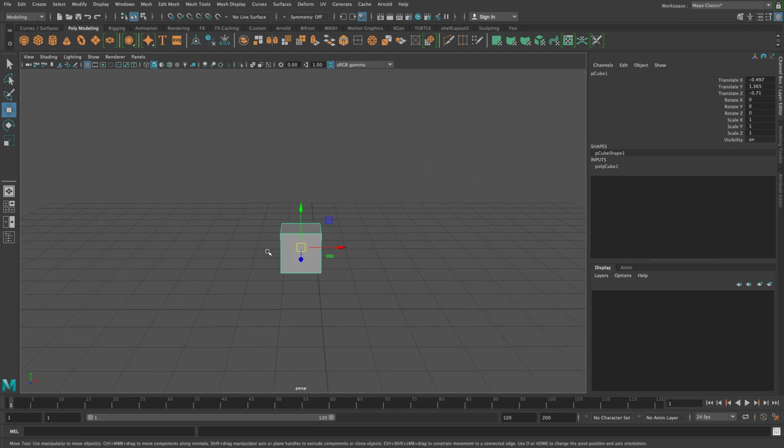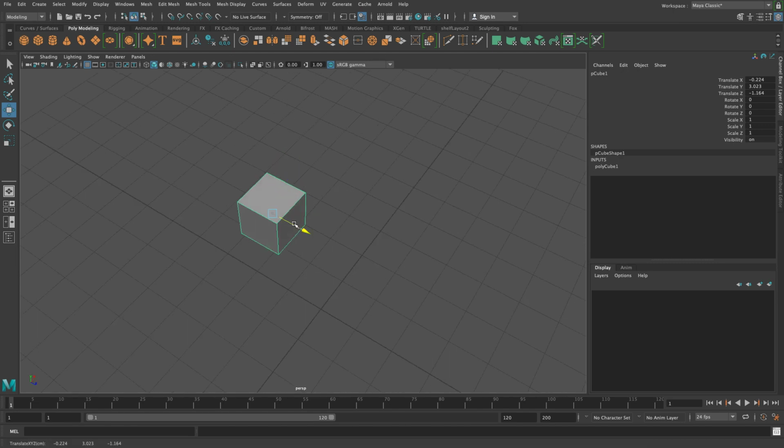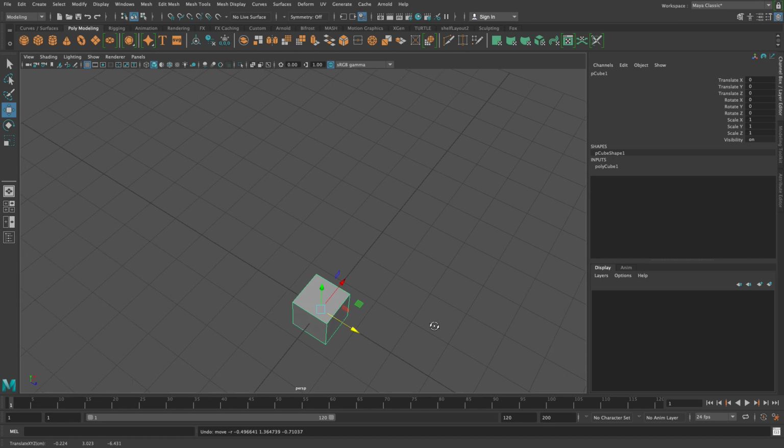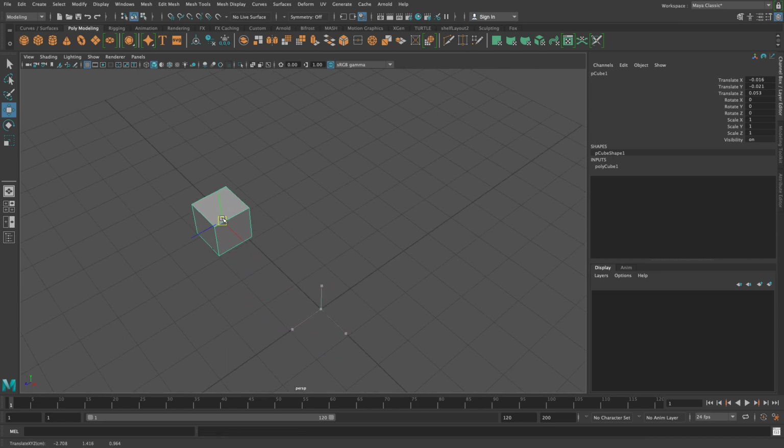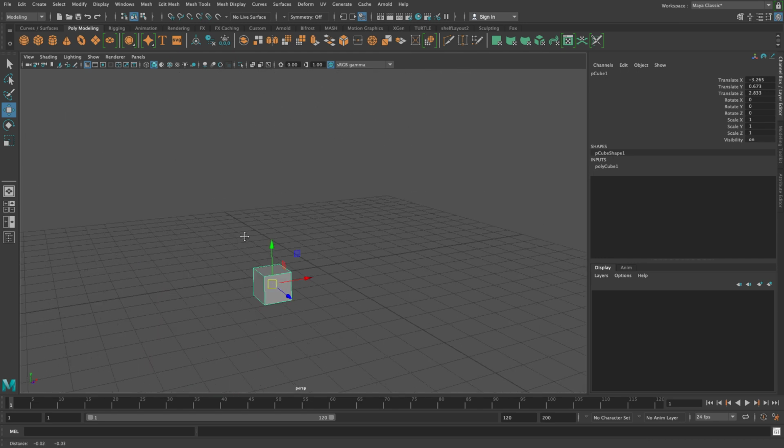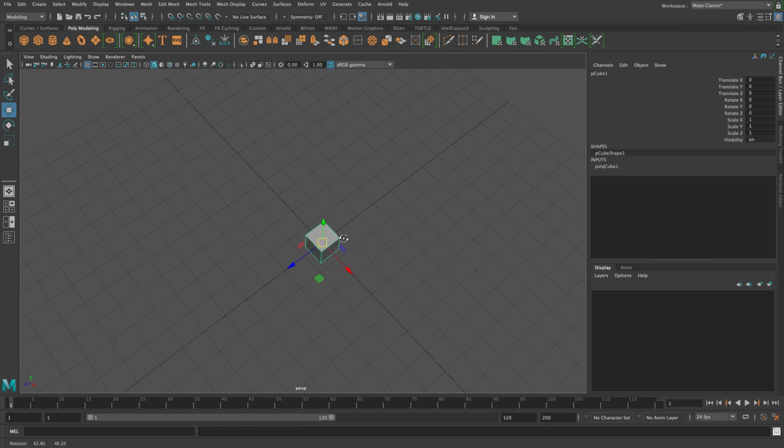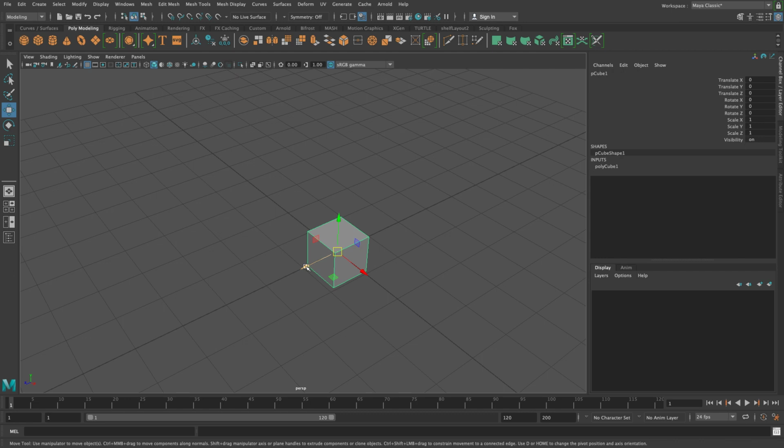So right now I'm moving along the x and the y axes, but using that middle box, there's always the chance this thing's moving backward in the z-axis in a way I'm not anticipating. So just be aware, if you grab that middle, sometimes it's moving exactly like you think it is, and sometimes it's not. If you want to be very specific with how you move an object, just grab the arrows. That's the best way to go about moving things in Maya.